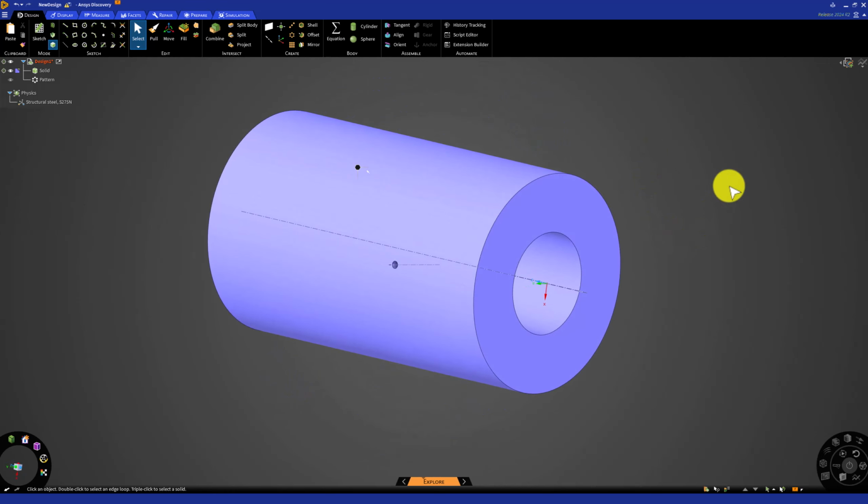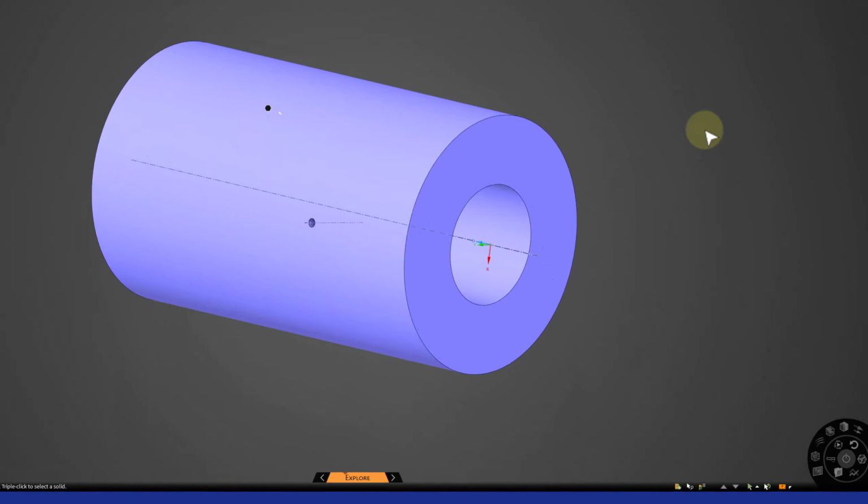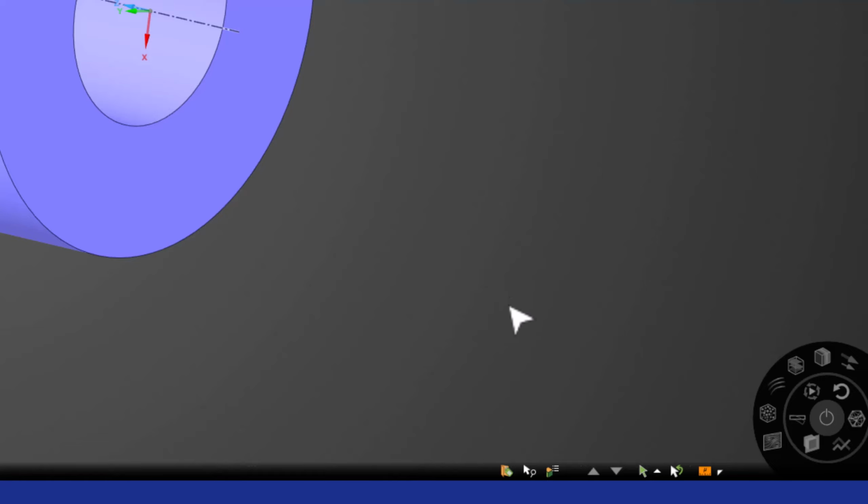The Fluent interface does not allow us to click on boundaries to apply the desired boundary conditions. This means we need to set up the locations on which these conditions will be applied now. We can do this using named selections. Start by selecting the Named Selection tool on the bottom right of the Discovery interface.